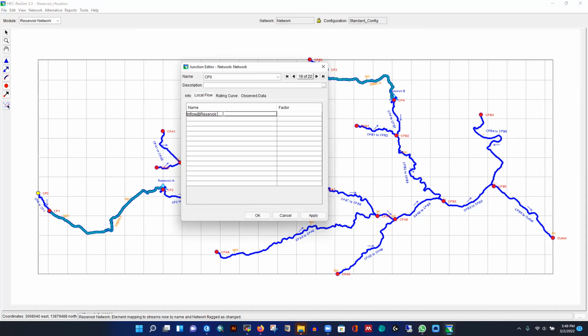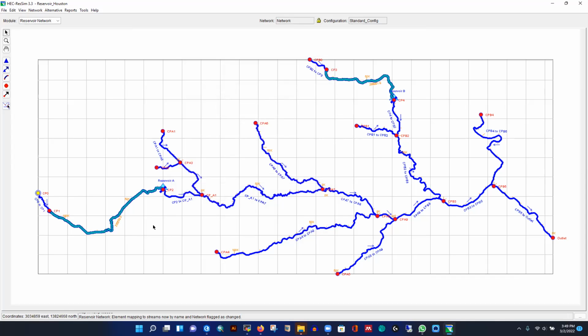So that is the description you can give. And what will be the factor? If I import any time series, since there is nothing coming from other streams, the factor will be 1, right, since we are not getting any outflow. But here we have inflow from other streams. So apply, so it changed the shape, see, and then we can even add the flow.